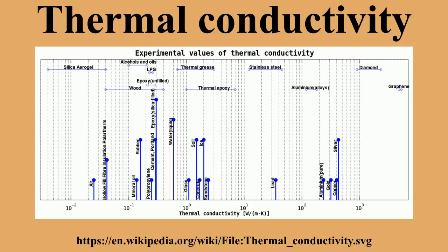High energy generation rates within electronics or turbines require the use of materials with high thermal conductivity such as copper, aluminium, and silver. On the other hand, materials with low thermal conductance, such as polystyrene and alumina, are used in building construction or in furnaces in an effort to slow the flow of heat, i.e., for insulation purposes.